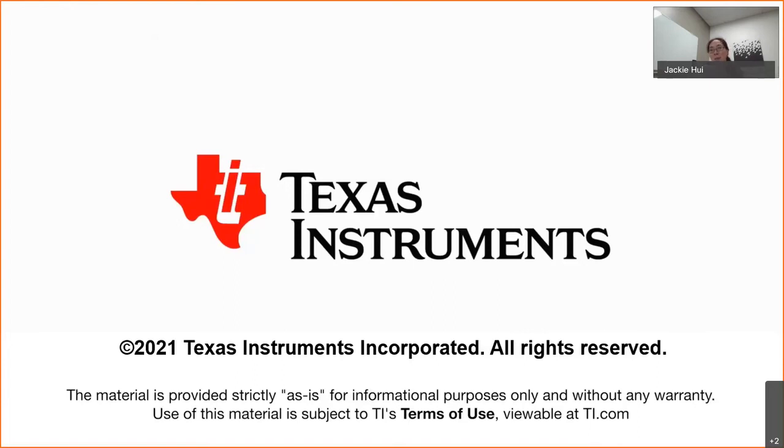Now, if that happens, and frankly, it happens a lot of the time, because the PCB is already there, you cannot change your layout. What you can do is try to slow down your switching. That's what the gate resistor placeholder will help with. You want to put even 1 to 2 ohm in place to slow down your switching and at least get to not damaging the driver, and then start your debug process.